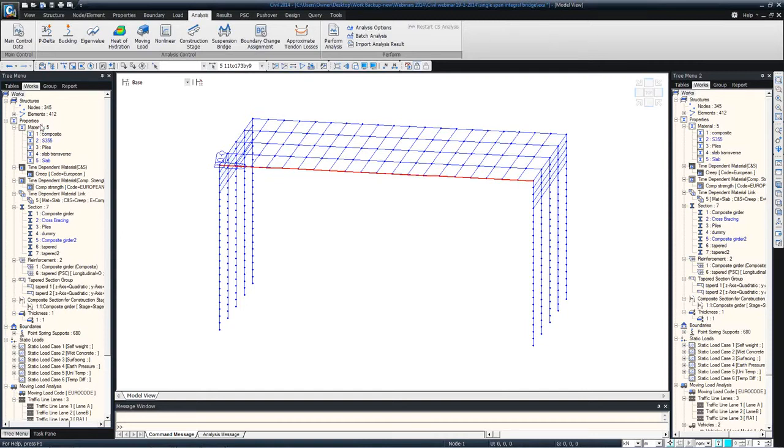We have another question related to the live loads. The question is, does it matter which reference beams we use as our starting basis for defining our lanes? It does not matter as long as you have defined the crossbeam type of distribution. You can use some other lane and define some different eccentricity to match the correct position of the lanes. So as long as you have defined the transverse information that you want to apply the loads via the cross beams, it gives you the same results for any reference beam.